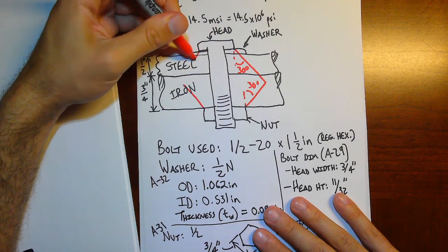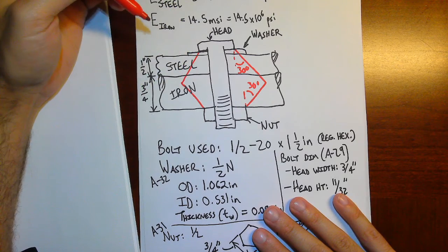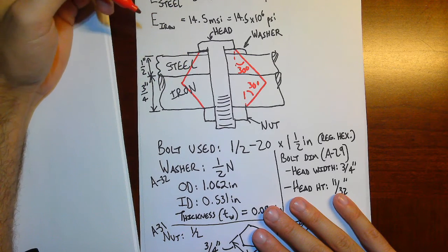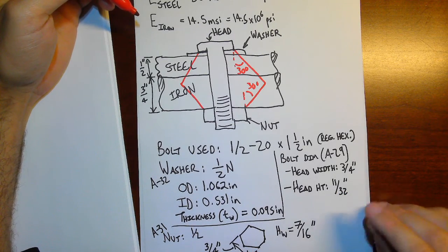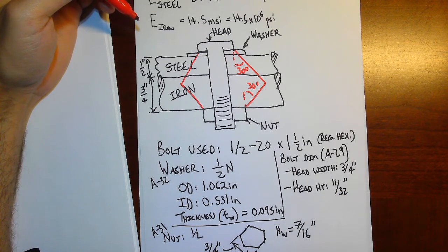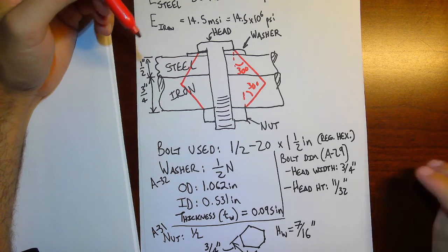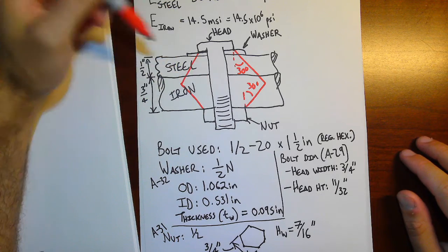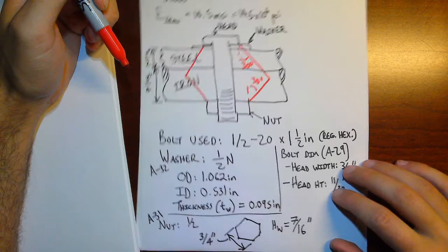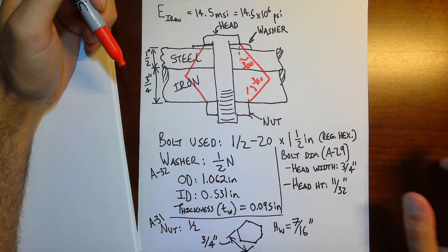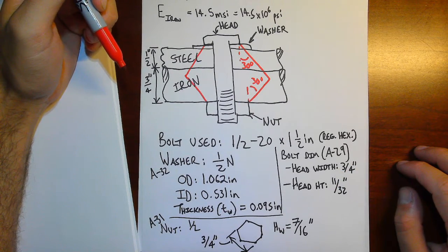And make this somewhat symmetric. So that's how the stress is being distributed inside the grip. We need to find out some stiffness based on the stress distribution so that we can figure out what the load is on all of these members and make sure that we preload it correctly so that it has the mechanical properties that we desire.